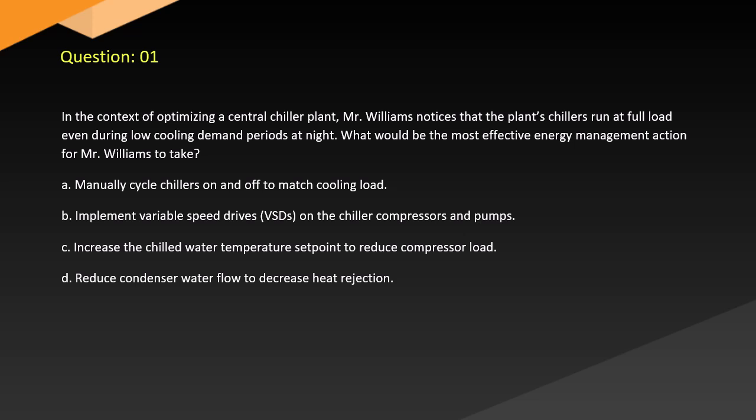B. Implement variable speed drives (VSDs) on the chiller compressors and pumps. C. Increase the chilled water temperature set point to reduce compressor load. D. Reduce condenser water flow to decrease heat rejection.